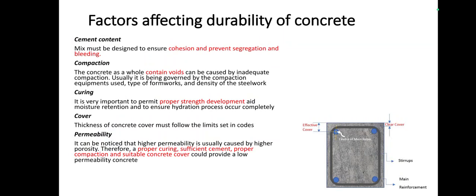Compaction. As I told, regarding this pore space, we should make a denser concrete, so compaction is very important. If you are not compacting the concrete properly, what will happen? It will result in air bubble formation, thereby air and water will easily enter, and the corrosion will start, so the durability issues will happen.